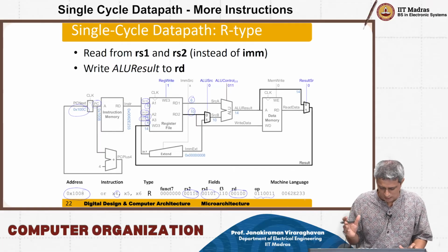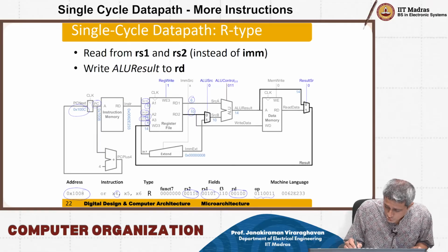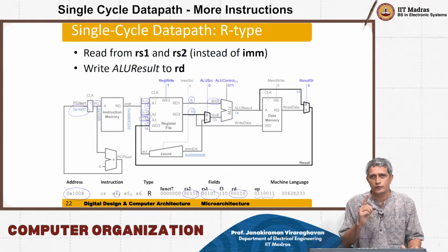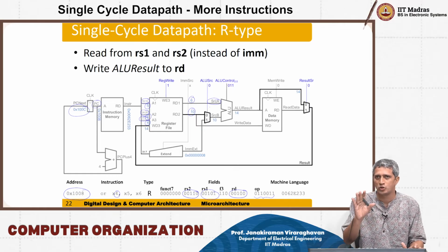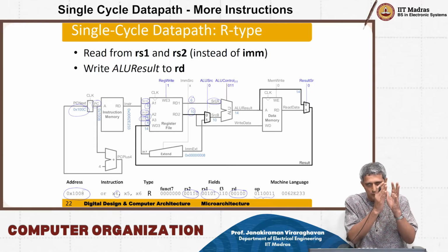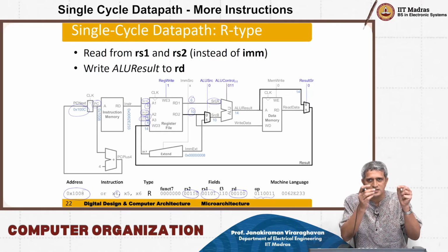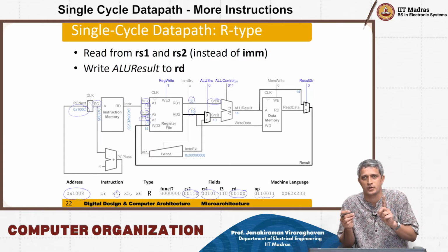So it is sitting there with some particular data. Now what you see is the source A for the ALU. The ALU is operating on 2 operands always, for most instructions, right. Source A is always the register data RD1 corresponding to RS1 of the instruction, okay.